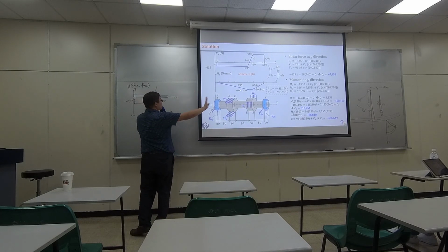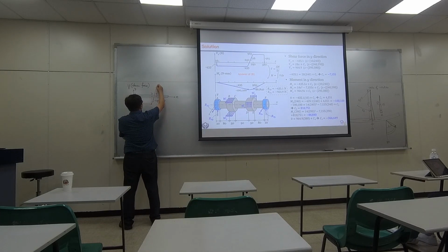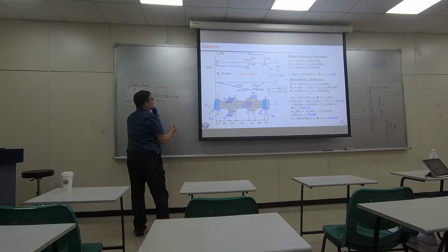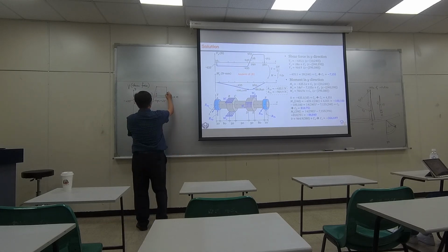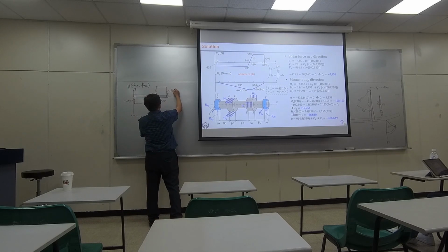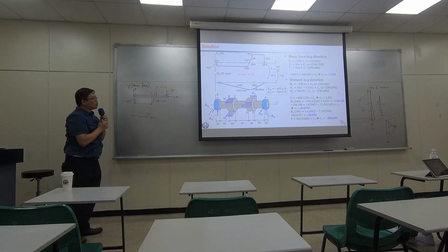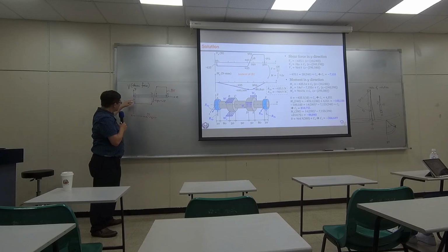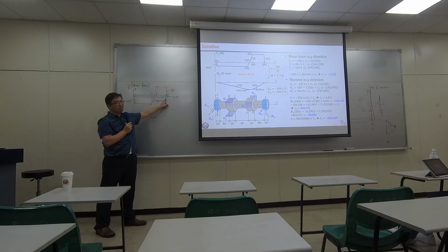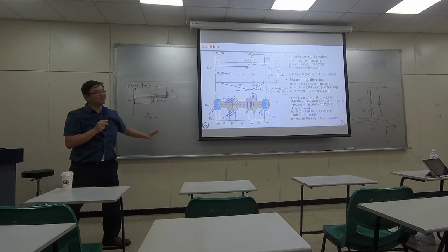Now when we are reaching point E, we'll keep on walking toward the right. Since from E toward the right there's no shear force, this remains the same until we reach the last point, and then we go down. The last point is called F, right here. And this amount is negative 965. So usually, when you walk from the very left to the very right, it ends up at 0. If it doesn't end up at 0, something was wrong. Somewhere you computed wrong. Okay?